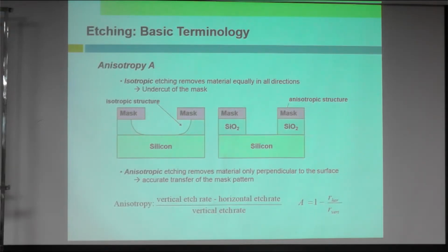This can be a consideration during the design process. If you know the thickness you want to remove, and that undercut happens, you might be able to calculate it in advance. If you dip into the wet etching process for a few minutes, for example, then you will get undercut.